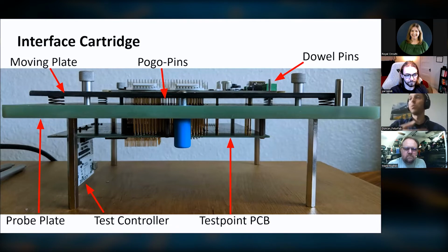But we definitely prefer to use the spring tip ones if it's a diameter that doesn't fit a normal size dowel pin. And do you prefer that those are plated or non-plated through holes? Non-plated is better, but plated is fine. And you said an overage of about 0.2 millimeters?